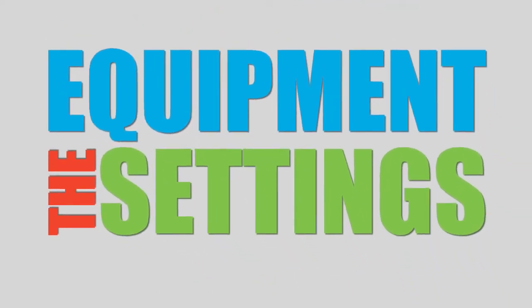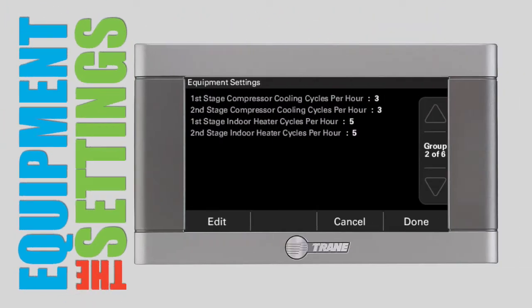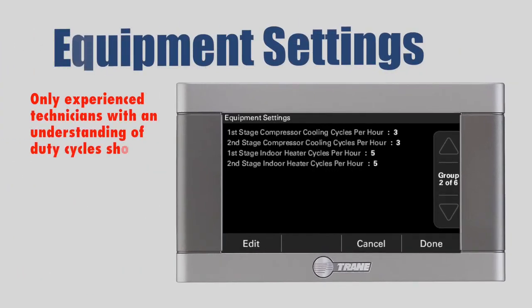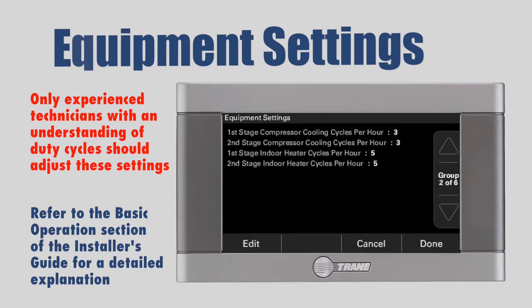If you press Done, you will exit the Installer Settings section before you have completed all of the groups of settings. Equipment Settings. Equipment Settings allows the adjustment of the cycle rate of the applied system. Note that only experienced technicians with an understanding of duty cycles should adjust these settings. For an explanation of cooling and heating cycles per hour, please refer to the Basic Operations section of the Installer's Guide. To accept the default settings, simply press the down arrow to move to Group 3, or to change a setting, press the Edit button.